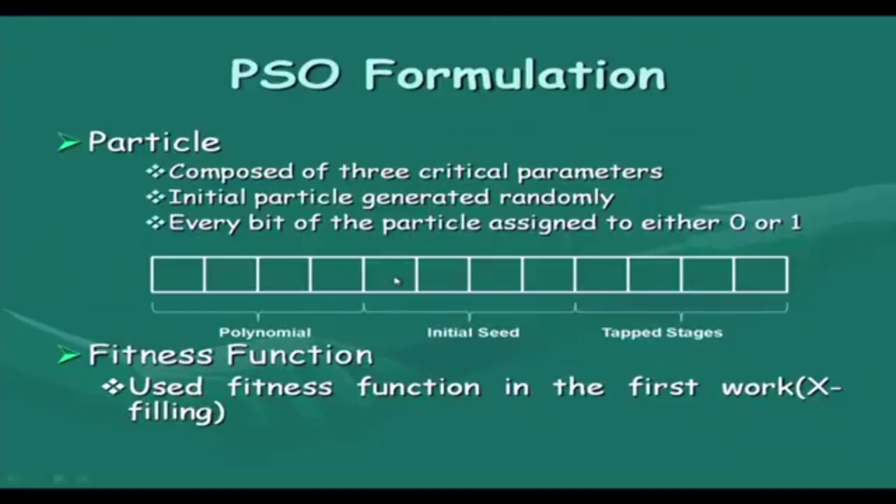Next, I need to specify the initial seed, and again there are n bits. So, these n bit values can be fed here. This is the initial seed value, the value with which the LFSR will start functioning.